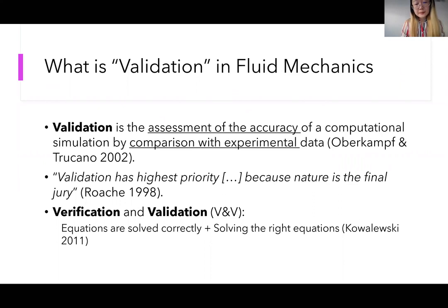good validation data set. And it is important to not confuse validation with verification, because the first one, verification, is a process to verify if the equations were solved correctly, so to verify the math is correct. However, validation is a process to make sure that we are solving the right set of equations, or we're solving the equations with the right numbers. So even if a set of equations or models are verified against an analytical solution, it doesn't necessarily mean that it will be representing the reality when it is applied to a real life problem. So that is where validation comes in.